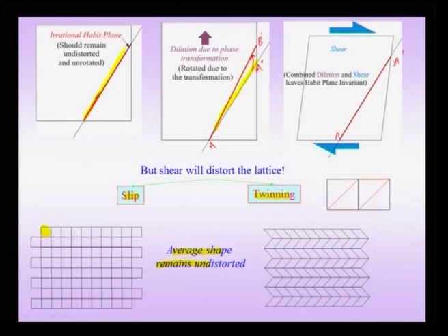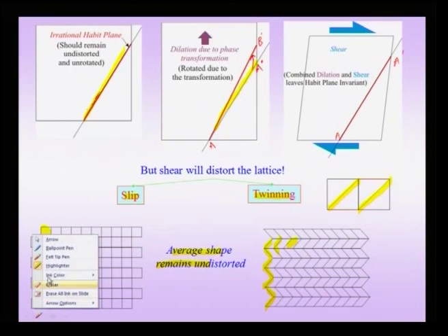So, I can have that, or in the right hand side, of course, you can see that these crystallographic planes are twinning, and this twin can accommodate my shear. Please note that this is not my new unit cell. What we have drawn here are these planes which are being reflected, and this shows the reflection of these planes. That means this is my twin planes.